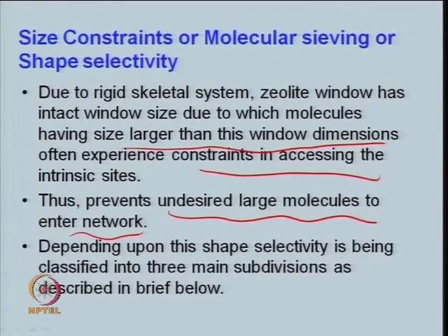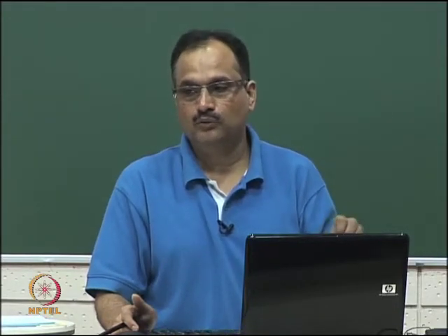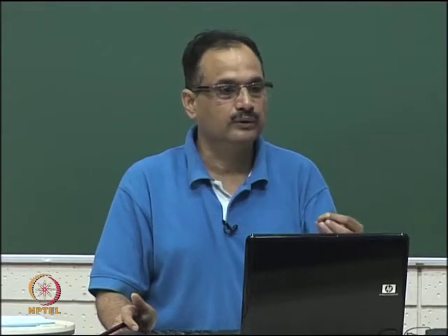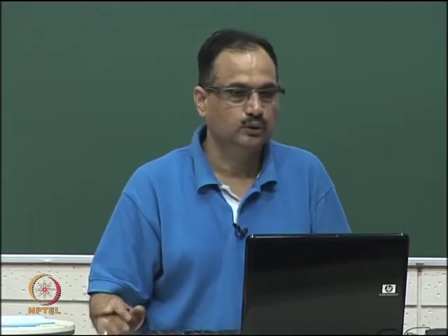That is good in one way if you have multiple reactant species, and some of the species present in the reactant are impurities, like sulfur molecules. When you have a hydrodesulfurization reaction, the larger molecular weight sulfur compounds I am talking about, like thiophene and dibenzothiophene, are large sulfur molecules. These can be separated, or sulfur removal can be done by using a selected type of zeolite material, just by adsorption. It can act as a sieving material. In a definite kind of zeolite material, the feed, that is the naphtha or larger molecular weight compounds, can be retained and cannot pass through that zeolite material, but smaller ones can pass through. So, it is like a cleaning or purification unit.